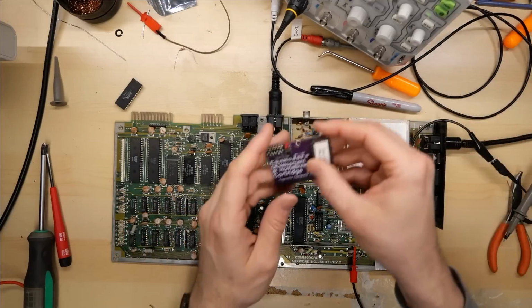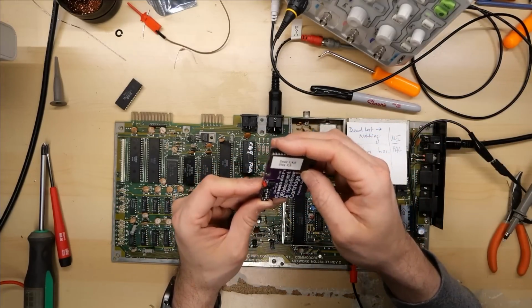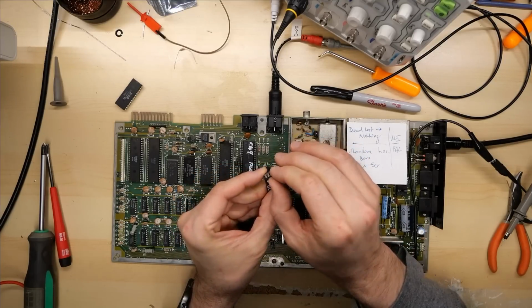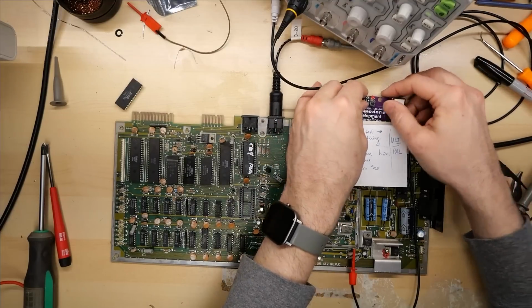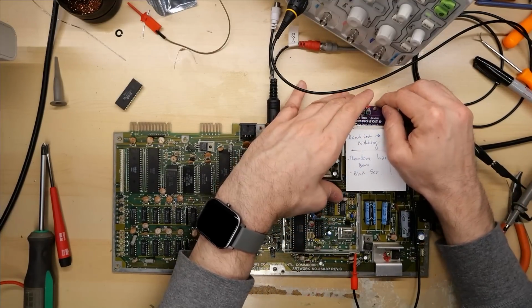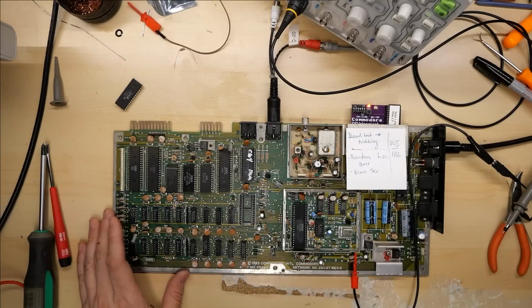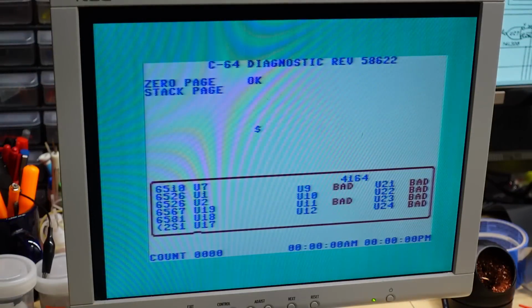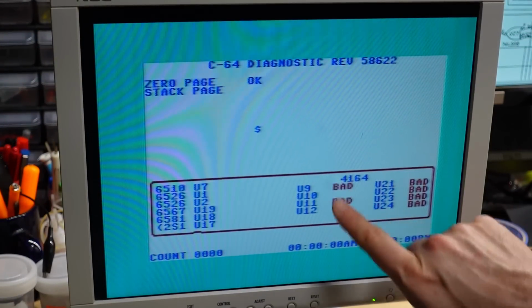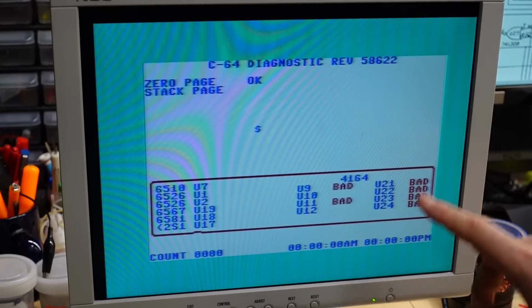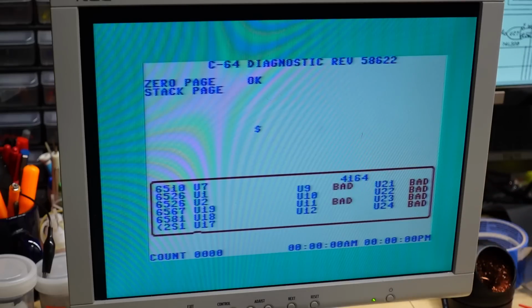So let's first off try the full diagnostic one, not dead test, but the one that requires the harness for full operation. Because as we learned in part 1, dead test is not a reliable RAM test. So here we go, and it was shifted down again. It's so annoying. It's obviously this monitor. Hey, look at that. Right away, bad, bad, bad, bad, bad, bad. Tons of bad RAM. And that is completely likely because of this crappy MT RAM that's on this board.